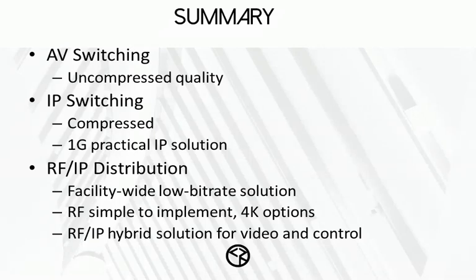IP switching is becoming more common, largely because the companies that make AV switching systems are now making IP switching systems. Again, it is switching because you have zero latency between frames. The signal will be more compressed, and there will be two solutions you can choose from. One, standardize on less compression and passing through cables designed for 10 gigabit systems end to end. That has its own issues as far as wiring, and many times instead of using copper, you find yourself using fiber for making the connections.